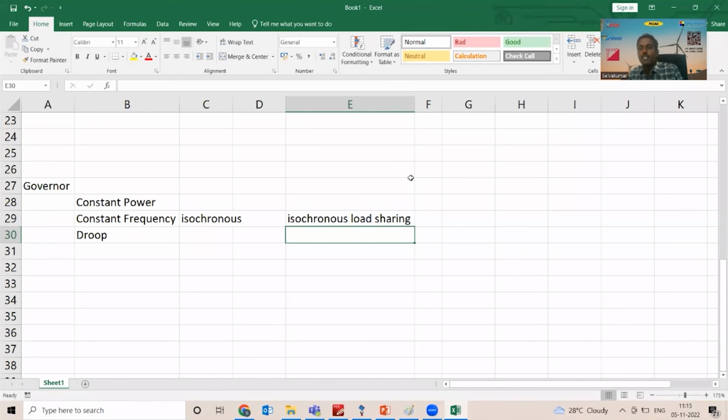You will be needing it, and probably as a system study engineer, you will have more challenge there in balancing real and reactive power sharing equally across all generators, even during sudden changes, right? It's important. One generator in ISO and the remaining generators in droop may not really work out, because that ISO generator will be taking whatever the sudden mismatch may be.